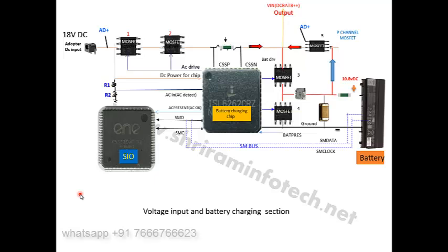Hi friends, today we are going to learn the battery charging section of laptops. In a laptop motherboard there are two power inputs. One is the adapter and the other is the battery, and this is the one output. These are the two inputs, one is here and one is here, and this section controls these two power sources, okay, and simultaneously it also provides a charging voltage.